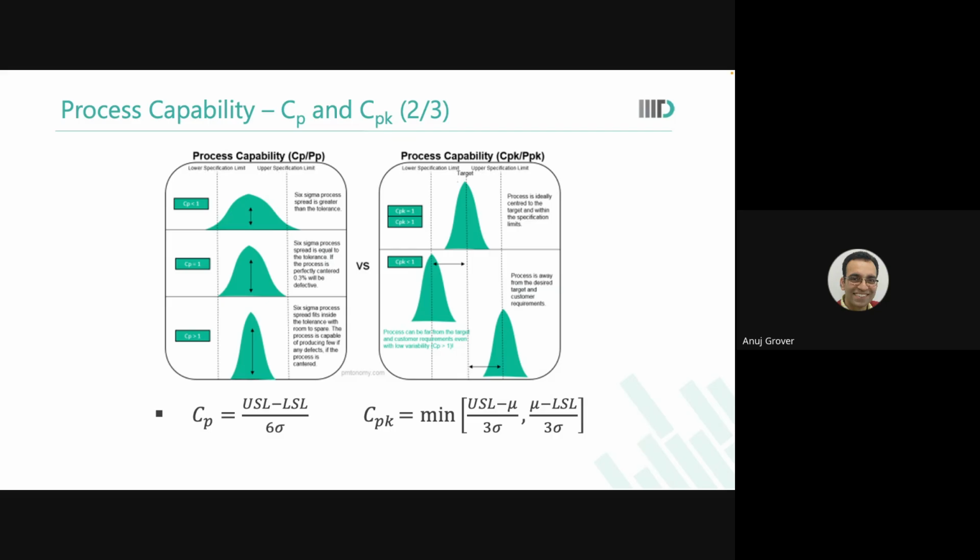So you will say, okay, my model and my statistics tell me that I need to qualify 4.5 sigma to meet this customer's requirement, because the customer is not using a big capacity, just a small number of samples, and I'm not looking at 100% yield either. So you say, I really need to qualify only 4.5 sigma. But since this is the first design, this is iterative, and this is just to showcase something to the users, let me qualify 5.5 sigma. I'm designing with 1 sigma margin.